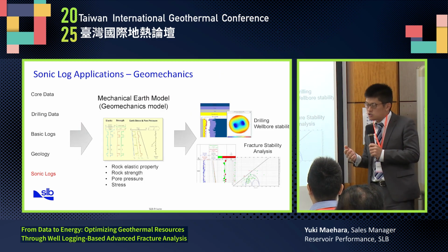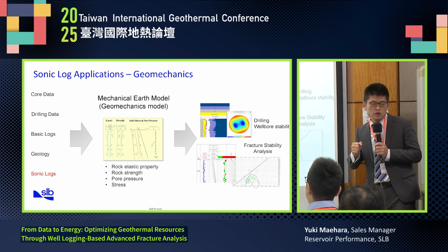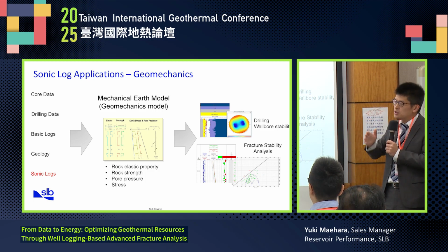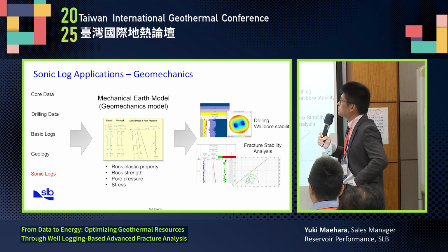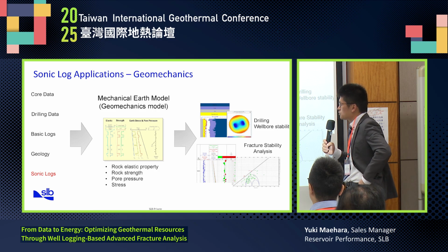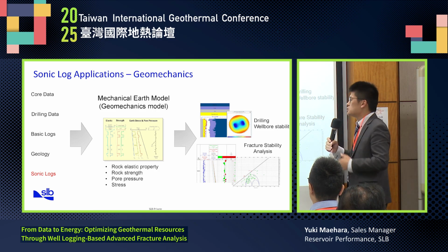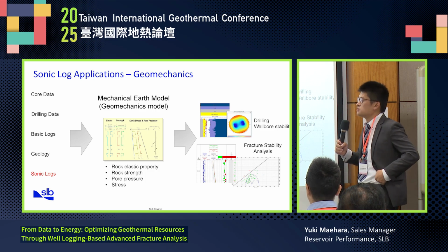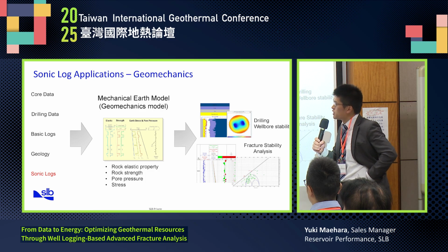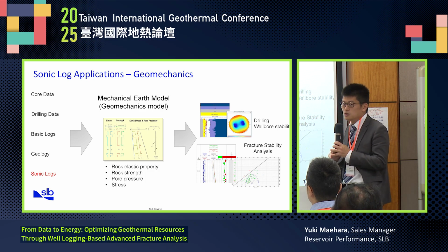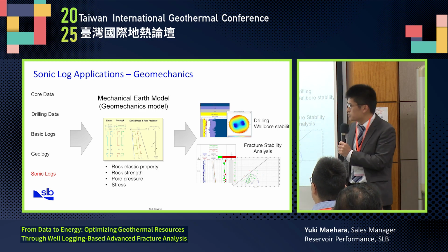The other approach to be considered is geomechanics. I think we have a massive presentation about geomechanics later today, this morning. But I would like to briefly cover how this geomechanics approach also works to evaluate fractures. Having core data, drilling data, or other basic log data, especially density, together with sonic data, we can analyze a mechanical earth model, meaning the geomechanical properties of the formation at every depth: rock elastic properties, rock strength, and pore pressure.